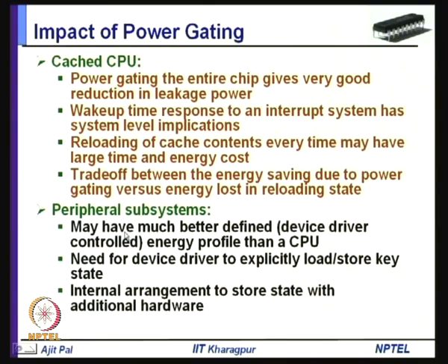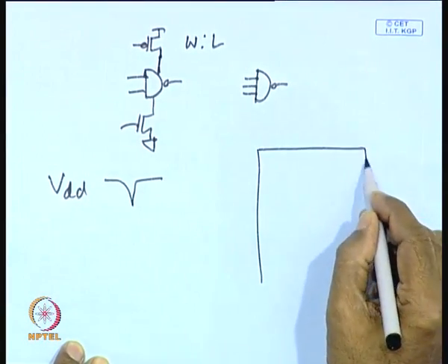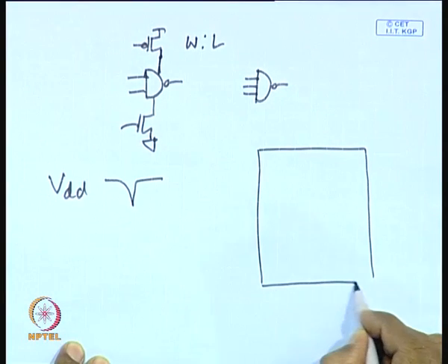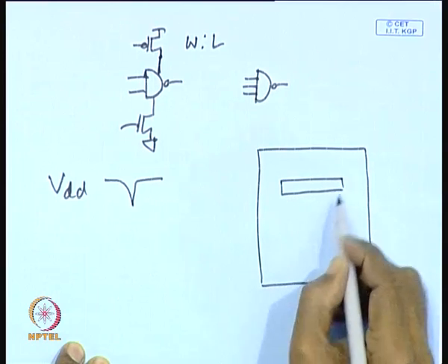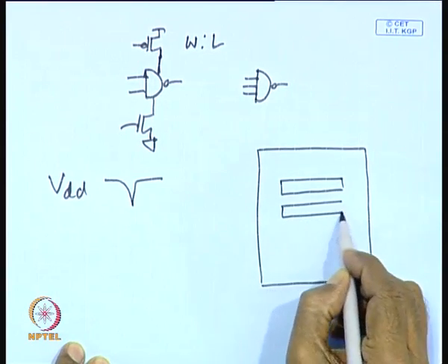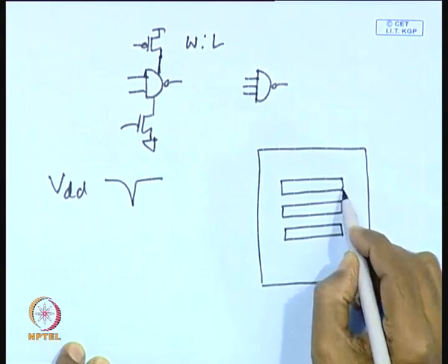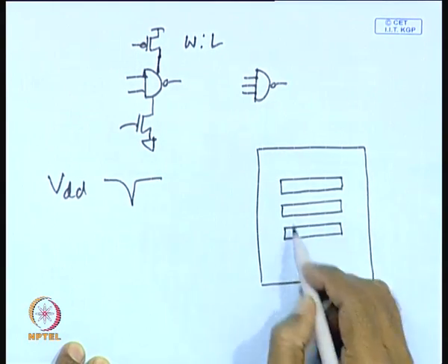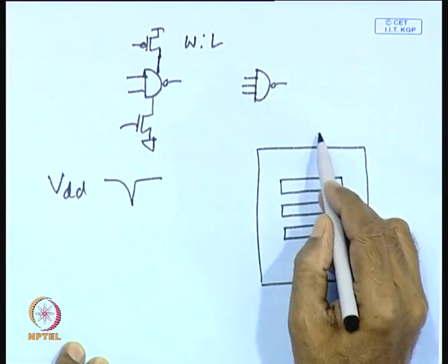You will notice that these programmable I/O devices, may be a DMA controller or an interrupt controller or whatever it may be, will have some registers which are part of those peripherals or subsystems. Those registers are to be initialized whenever you make them active.